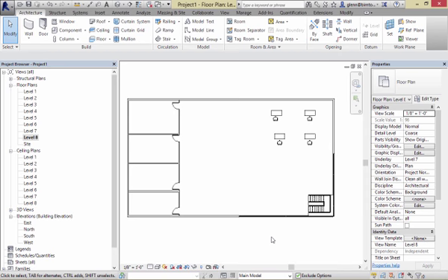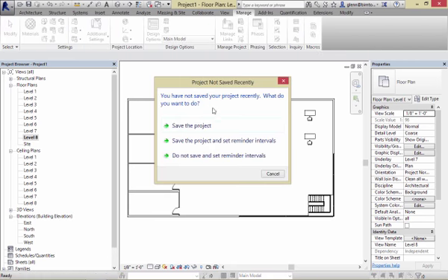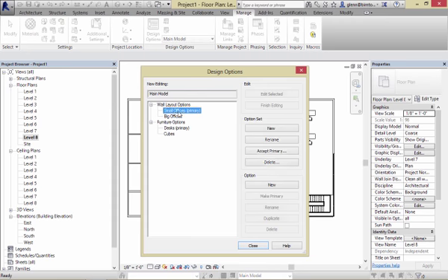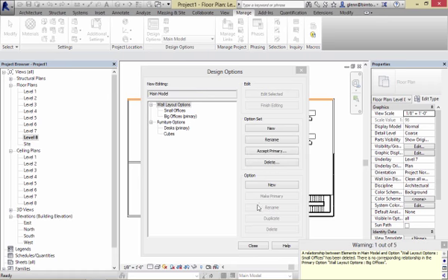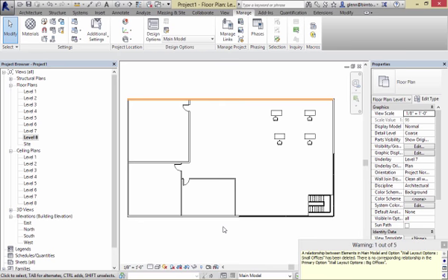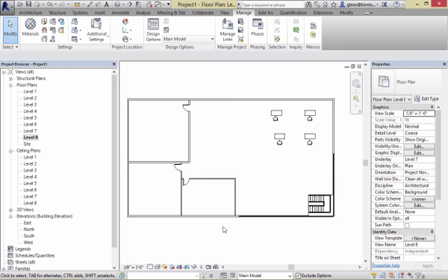what you can do is go to the design options and see how it says small office primary? To change, take big offices and make that primary. Okay. If you do that, the main model now shows big offices as opposed to small offices. Here it's sort of complaining because of a wall joining in that. It's a little upset about that, but that's just a warning. We'll let that slide for now. Okay, so whatever's primary is going to show up in the main model.